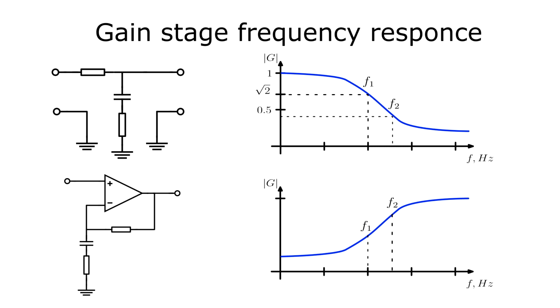frequency response graph. In the frequency range from 0 to f1 for the shelf filter, the gain value is equal to 1, which means that the op-amp has 100% negative feedback and behaves like a buffer. For frequencies greater than f2, the amplifier has a constant amplification factor determined by the voltage divider formula. The slope region between f1 and f2 smoothly amplifies the input signal. It may not be immediately obvious. We can achieve a high-pass frequency response by using a low-pass shelf filter in the feedback loop.